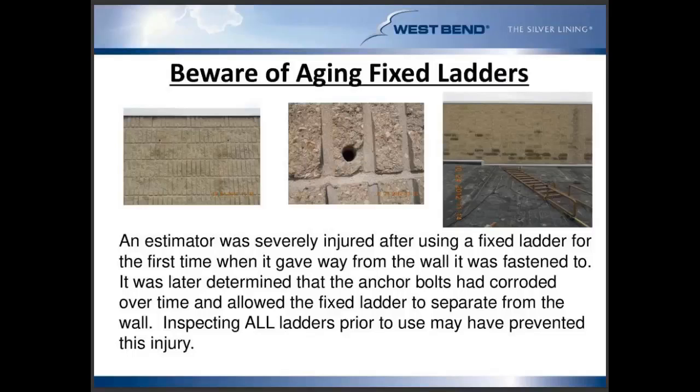This was a nasty injury that occurred several years ago where the actual fasteners or bolts to this masonry wall had rusted and corroded over time, and as the worker was climbing down, the ladder pulled away from the wall and resulted in a serious injury from a fall. So again, we need to inspect our fixed ladders as well.